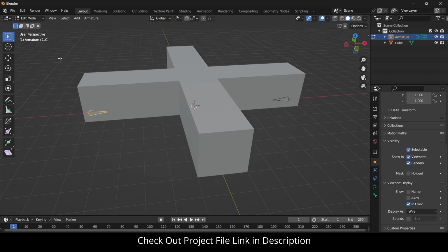I am going to parent it to someone. So I will select this bone, and by pressing Shift select this one, press Ctrl P, click on Keep Offset. Now select this, press F2. I will type 2 because it's my second bone. Press R because it is on my right side. Press P because it is the parent one.